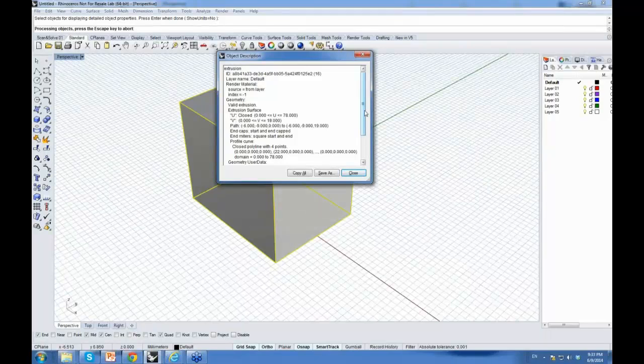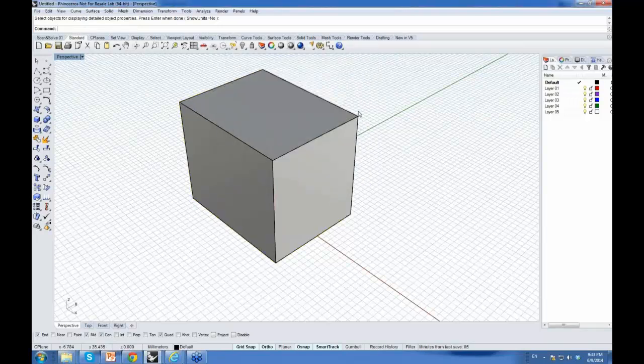Usually I think they're actually straight profiles. Previously, in Scan&Solve prior to 2014, you would have to use the convert extrusions command to convert this from a lightweight extrusion to a polysurface that could be operated on in Scan&Solve. But we can do it directly in Scan&Solve now.